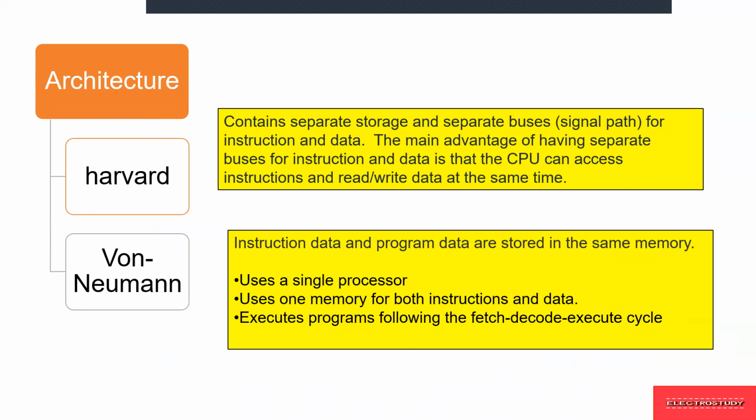Let me explain: when data like 0H, 03A is transmitted from the input part, it is stored in a particular memory, and the instructions like add, multiplication, division are stored in another memory. When the data and the program are stored separately, it is known as Harvard, and if they are stored in the same memory space, it is known as von Neumann.